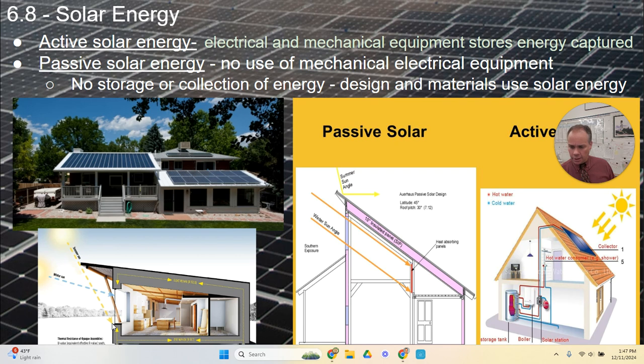So the sun's radiation, when it's at its peak, most intense, is not actually entering the house because this overhang is shading it. And that would minimize the use of air conditioning in the summertime. However, it's designed so that in the wintertime, because the sun is lower in the sky, this solar energy is able to get into the house because of the different angle. It can be stored in concrete, which, as it heats up, can hold on to that heat.